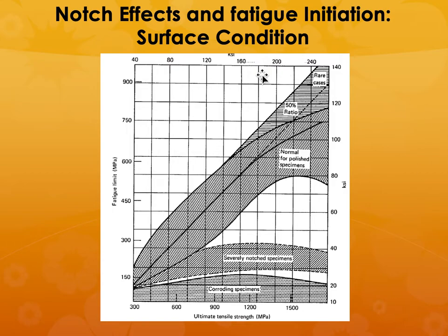So from these set of curves, you can see that the fatigue lifetime can decrease drastically with respect to normal polished specimens and then severely notched specimens. So severely notched specimens will have much lower fatigue limit than compared to normal polished samples.